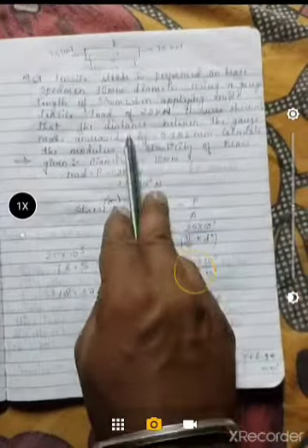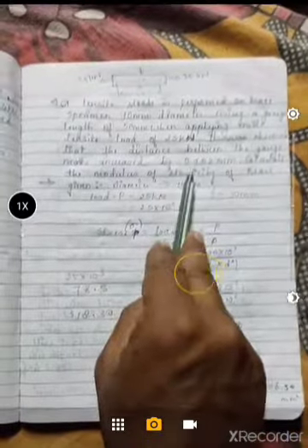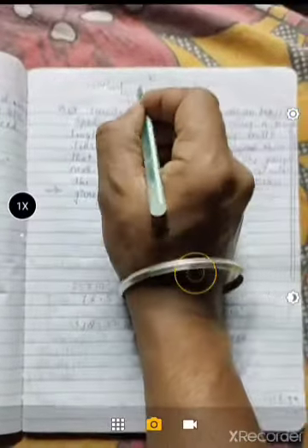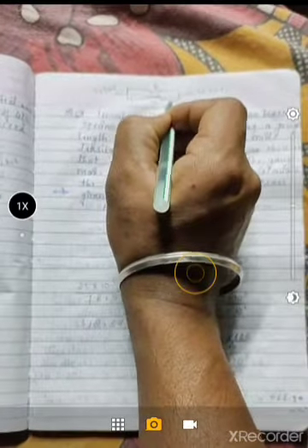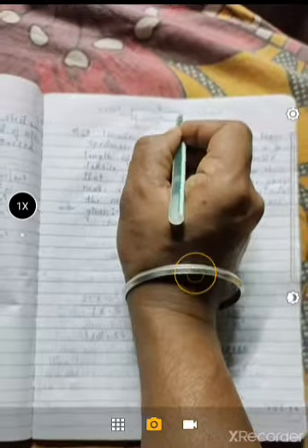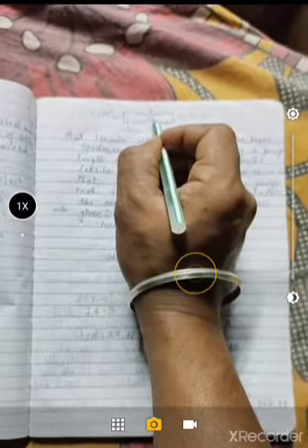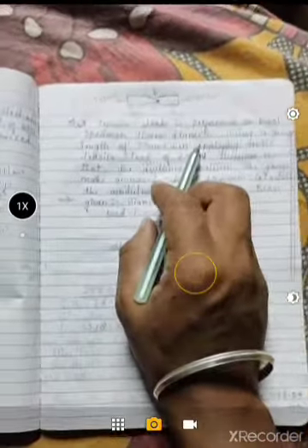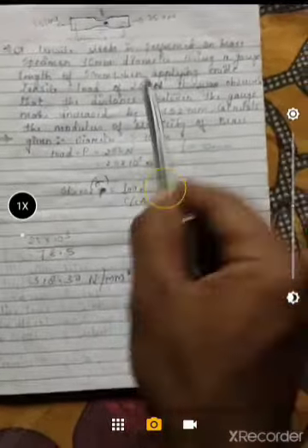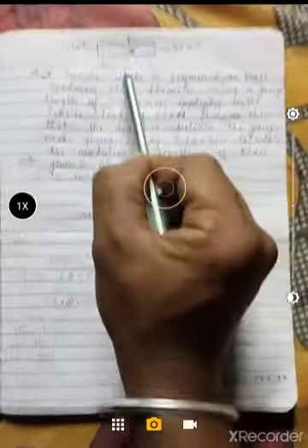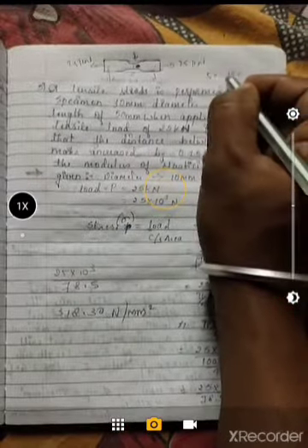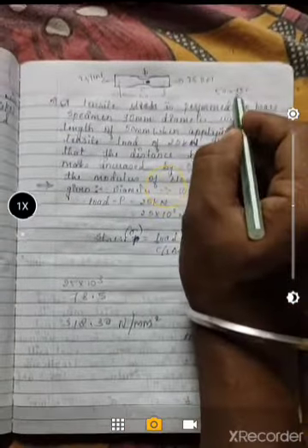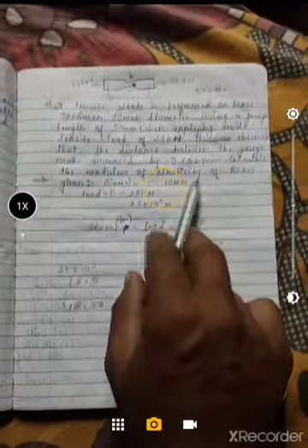It was observed that the distance between the gauge marks increased by 0.152. When you are applying the load here, the specimen is like this. This is understood in the MT lab. So this diameter is almost 10 mm. When you are applying the load, the length increases, it becomes 50 point how much? They are given 0.152. So up to 0.152. Calculate the modulus of elasticity of the brass.